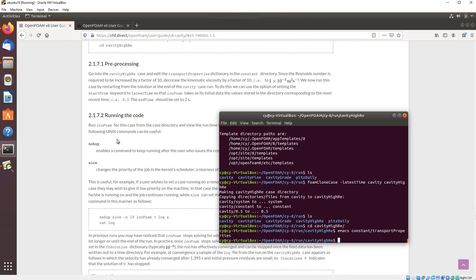So the solver will have more and more difficulties to calculate that, because the higher the Reynolds number, the less the fluid behavior conforms to what we saw previously. You'll start to see whirling in the fluid, etc. So the solver will take more and more time to solve this. Afterwards, we'll have to use a turbulence model and another solver. But for this case, we'll just see what it does, to see if it's really longer to calculate.